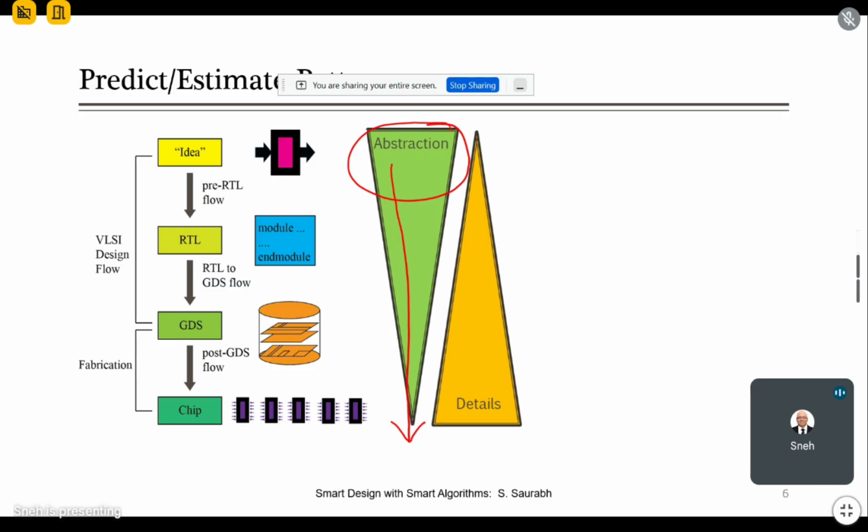For example, we have written an RTL code, right? And RTL code needs to be synthesized, right? Now, synthesis means that in the RTL code we write something like y = a and b, right? Now, if we write something like this, then this will be synthesized to an AND gate. You have A, B, and Y, right?